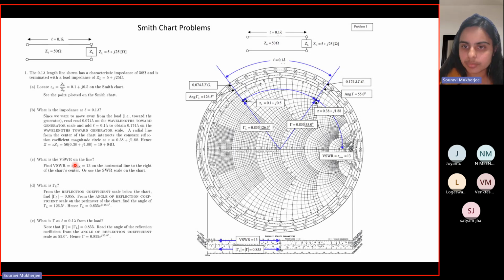And there it tells you about the maximum resistance that can be present in the transmission line. Now we know that as the radii of the circle decrease, the resistances increase, right? So this circle, wherever it cuts, it would cut at 2 points. If you extend it further and make a complete circle, it will cut somewhere here and also somewhere here. And this line is the purely resistive line.